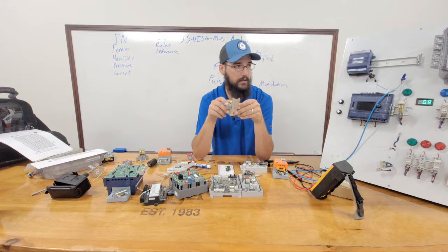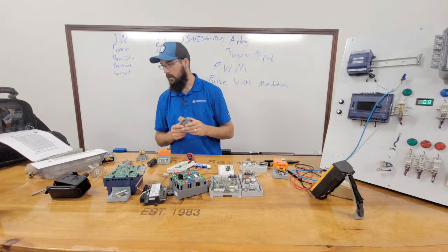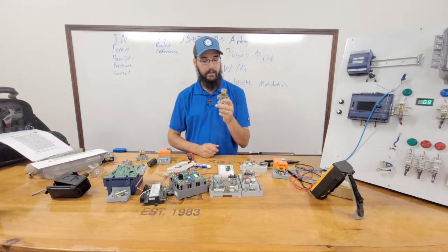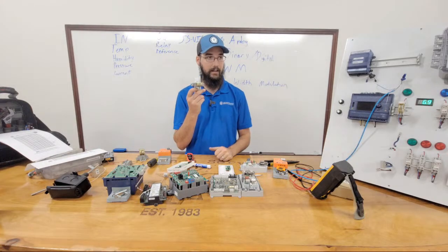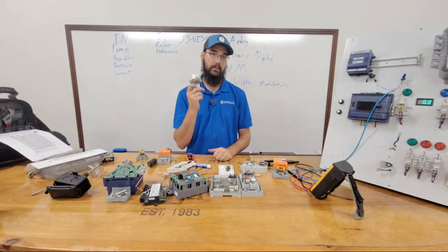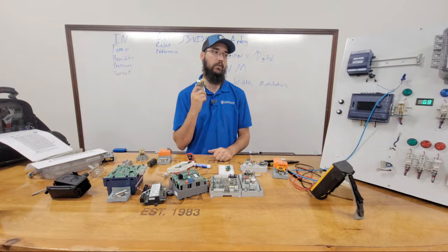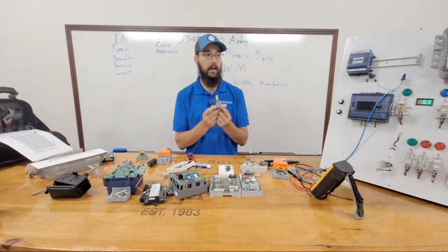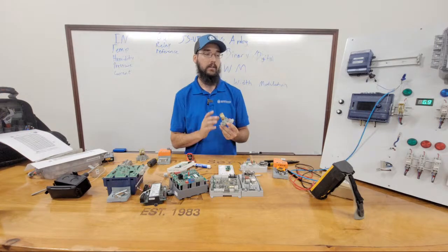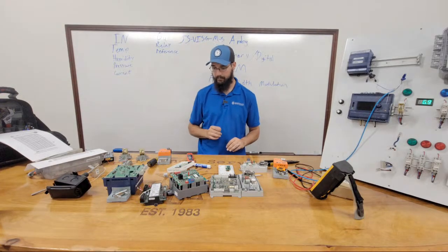They've got a termination number. I forget the exact one off memory. Anyway, that's my recommendation on this. So if you're walking up and you are finding these are failed, and they're trying to run actual loads through this, whatever the load may be, I highly recommend you consider talking to the customer and seeing if they would be willing to turn this into an ISO, and you rewire that circuit to have an actual contactor or something else that'll handle that load better.